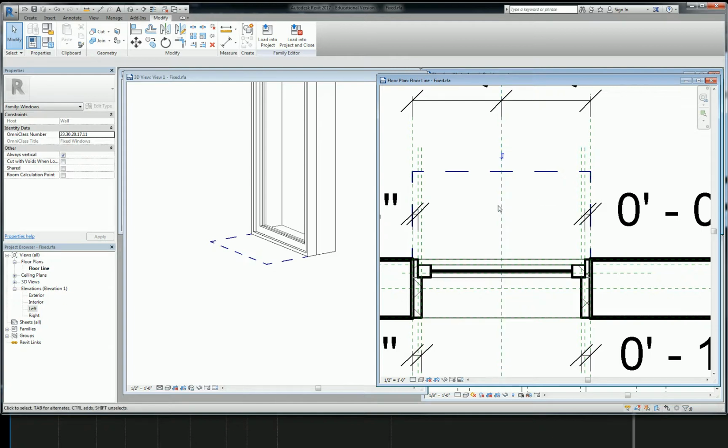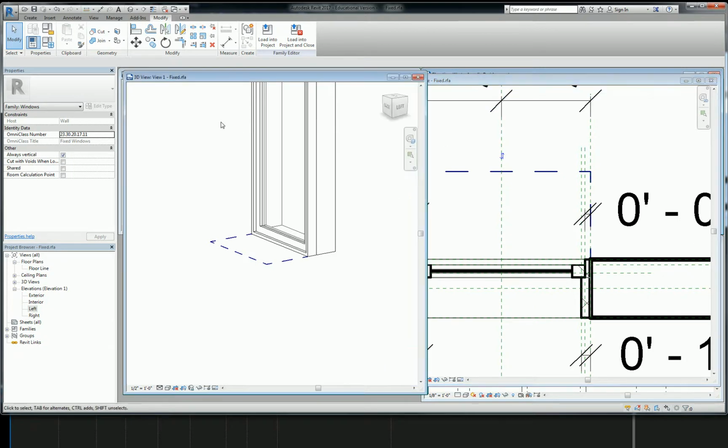to make sure it's working properly before I put that little triangle in there. What you need to do with a family is, when you open that family, it's a separate file, and you have to load it back into your project. Okay. So how do I want to describe this? When you load it back into your project, the new version loads into that project only. And if you're trying to keep what you've modified, like save the family as a separate file, you need to do a save as. But don't worry about that yet. We'll get there when we get there.